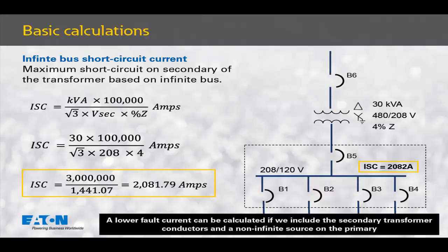The bigger impact will be if our actual transformer shipped and installed has an impedance greater than that which we used in our calculations. That's the more significant impedance in this situation. We're approaching this as the worst case scenario, as we don't want to have to make changes after the fact. We don't want to see as-built drawings come in with impedances of transformers lower than what we anticipated, or conductor runs that are less in length than what we anticipated, because that will increase the short circuit currents. We take this as a worst case scenario to minimize our exposure and risk.